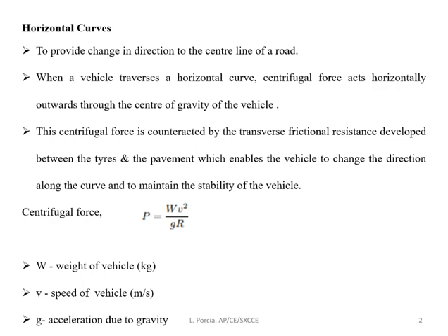We know while a vehicle moves on a road, a frictional force will be developed between the tires and the surface of the pavement. And this frictional resistance developed in the transverse direction helps in counteracting the centrifugal force. And this enables the vehicle to safely move along the road on a horizontal curve and to maintain the stability